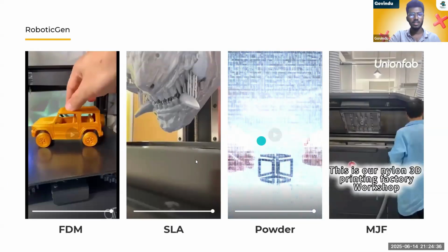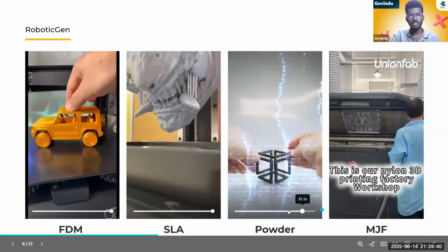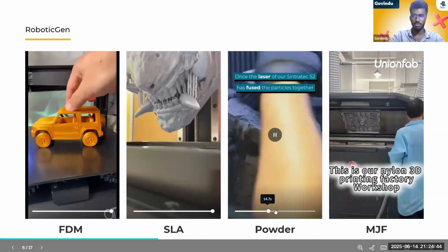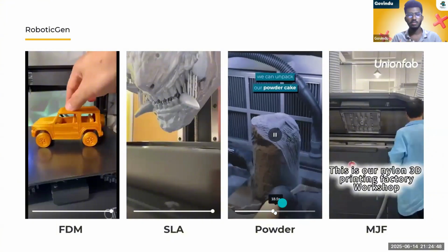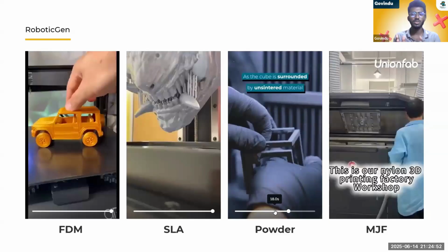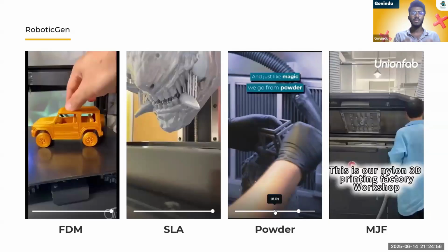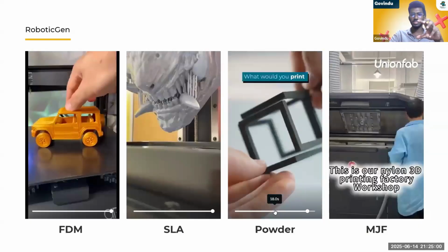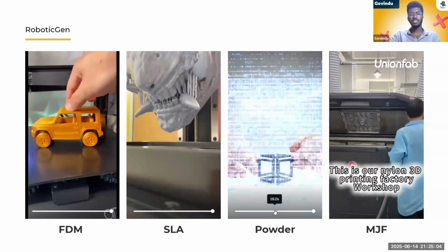See, instead of resin as in SLA, in this powder process the particles fuse together, and we can unpack our powder cake. All we have to do is clean the part of the residual PA12 powder. Since the cube is surrounded by unsintered material, we do not need any support structures. And it can get this 3D design.